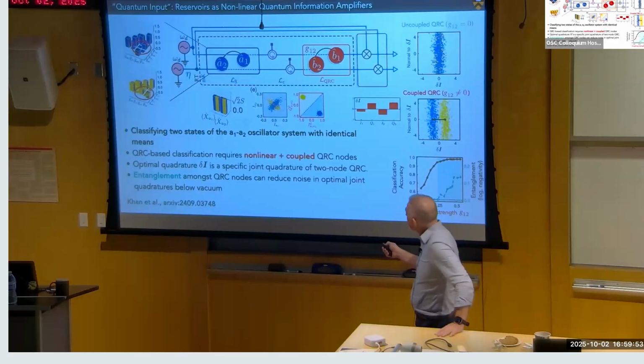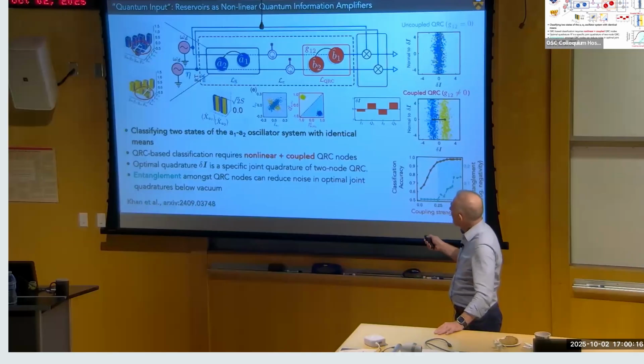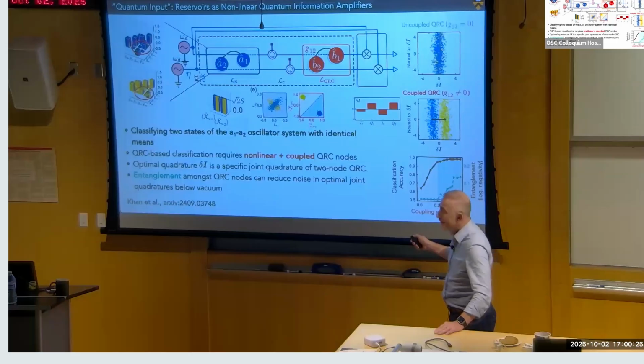And what you see is that the mean of these microwave signals is the same, and the distinction is in the noise, okay? And in classical signal processing, what you would do is you would do many, many averages, and you would take the square of these signals, and then they would separate, and you would be able to distinguish them. But that is very difficult with these microwave signals because there's a lot of thermal noise that is added in the processing chain. This never works, okay?